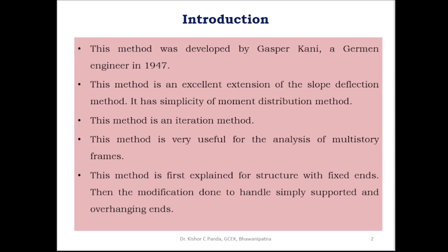This exercise is carried out for all the joints in the structure one by one till the distributed moments in successive iterations are almost the same. And this method is first explained for structures with fixed ends, then the modification done to handle simply supported and overhanging ends.